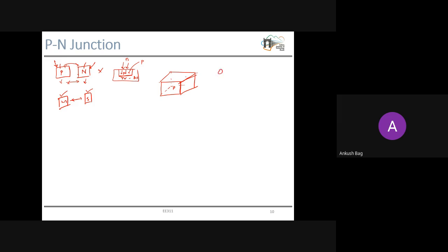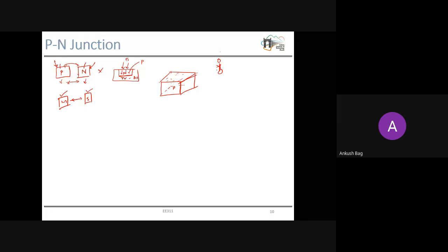That means the top silicon layer will have dangling bonds, or bonds which are not satisfied, because there is no other silicon at the surface. So all the surface silicon atoms will not find another neighboring silicon atom to complete the covalent bond. This bond is called a dangling bond, and this dangling bond will create the problem.